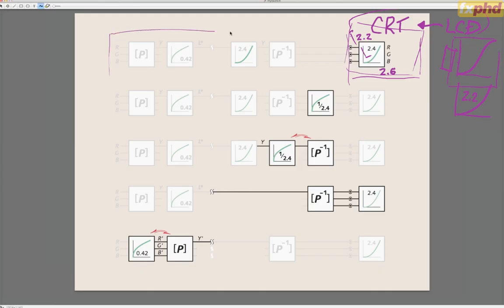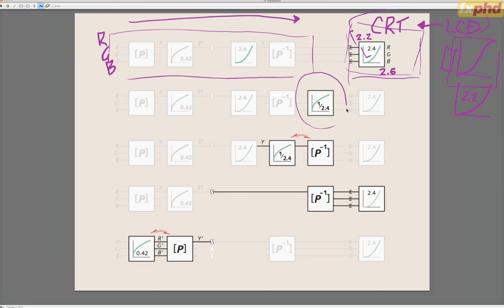So this scheme that the color scientist was comfortable with, transporting RGB information from an encoder to a decoder, has to be corrected by basically reversing that curve out of the CRT in order to be used in that block diagram. Now, the video engineers in the early days, long before LCDs, were faced with very much this sort of consideration. They knew how to do the correct thing in color science. They knew that the 2.4, 2.2 function of this CRT would force this operation to be performed in the electronics of every decoder.